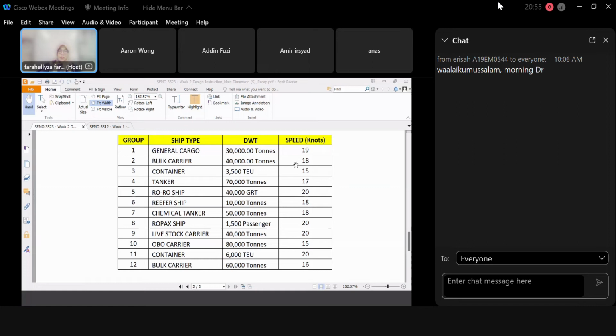If you look at the body of the ship, you will see what we call the load line symbol. With that load line symbol, they have NK or ABS or LR or DNV. That determines the class of the ship, and it is recognized internationally by the classification society. That is additional. But usually the typical owner requirements are ship type, DWT and speed.